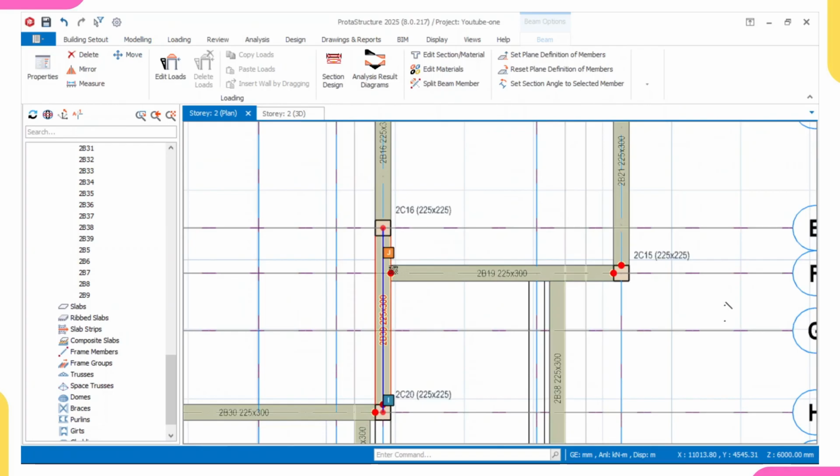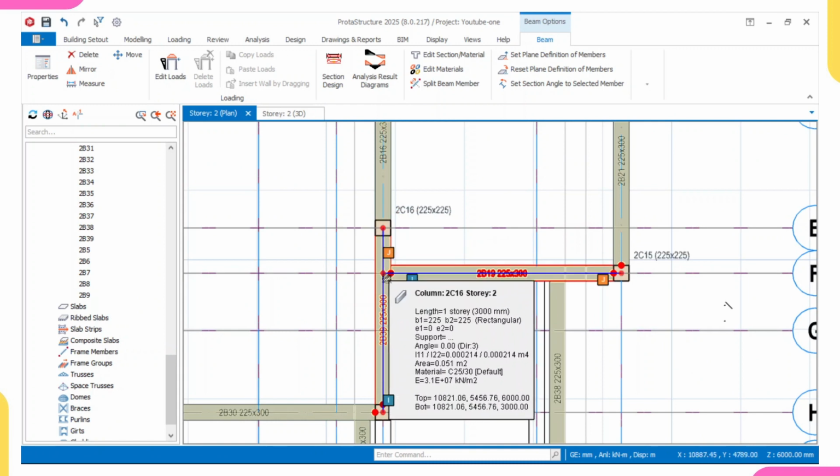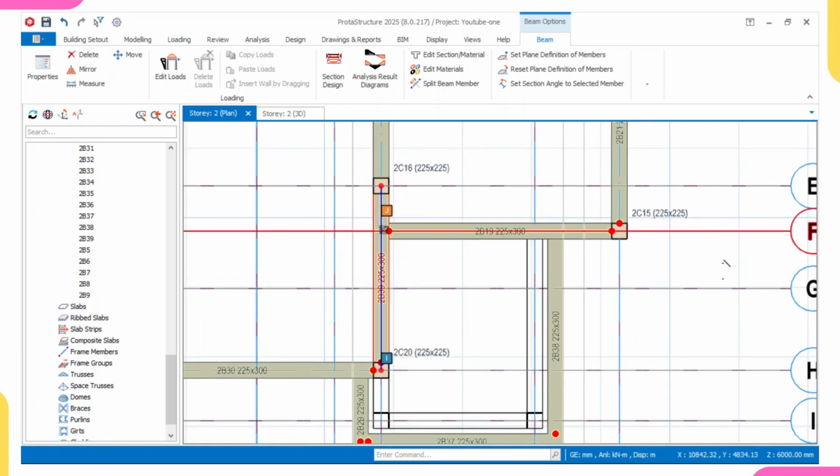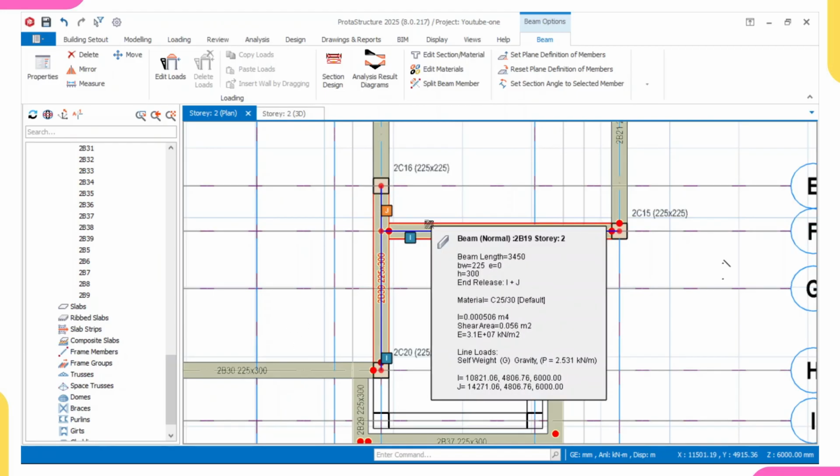What it means is that if you say yes, you want to split it, that means this beam will now run from here to here and stop, then continue again from here to this point. But no, if you do it like that, I don't think this beam will no longer be the one carrying this. So I want this thing to be a straight beam. So it will be that it is carrying this secondary beam. So that's why I say that they should not split it for me.